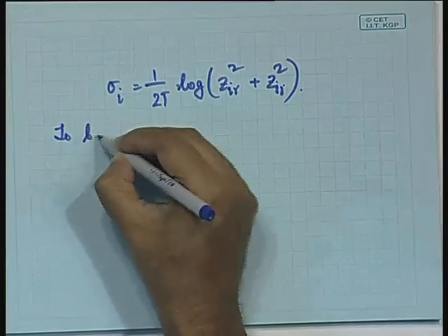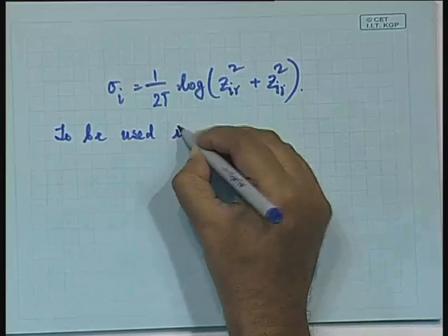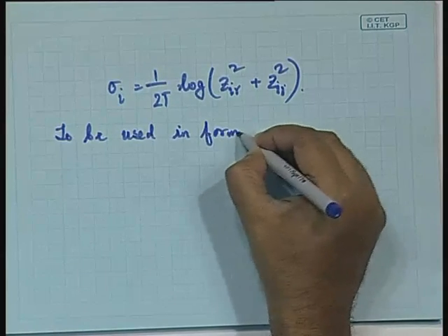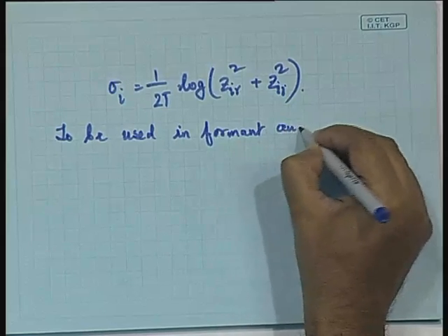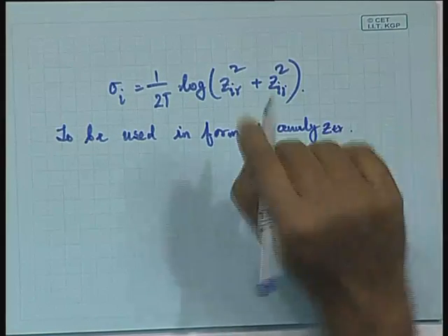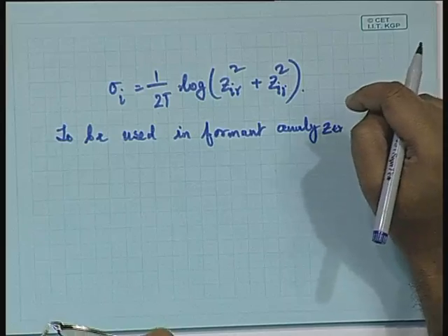Now, one aspect we have to consider for a vocoder realization is how to obtain the formants. That is going to be a very important aspect. So far, although we have talked about the pitch period estimation and the solution of the predictor coefficients, we have not essentially addressed how to analyze this, that is, how to obtain these formants.